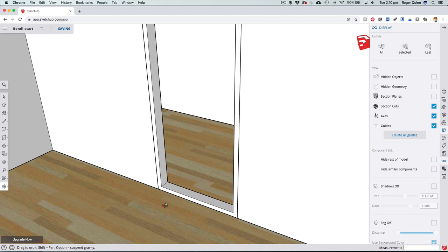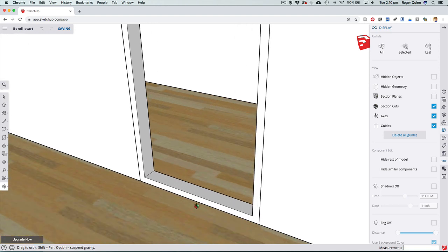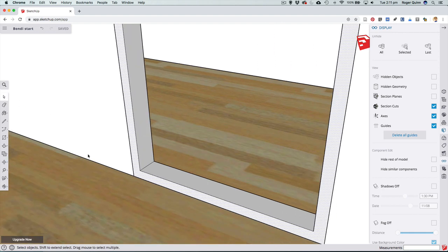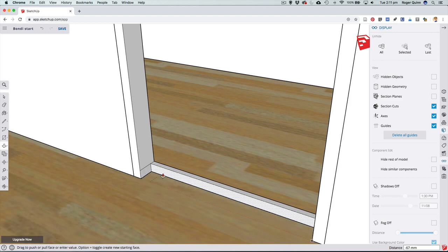Okay, so the frame should go straight down. So how do you fix that? Well, it's pretty easy. I'm still in edit mode, by the way, for this, so I'm just going to get my pencil, draw a little line down there, and draw a little line straight down there. Okay, that allows me then to grab that little front face of just this step part, get the push pull, push it back until it disappears.